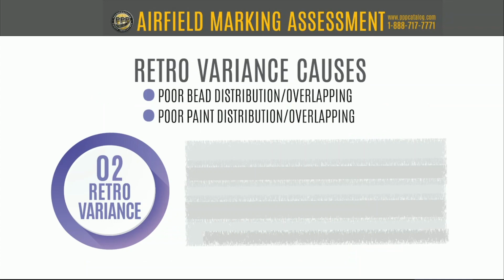If I had a choice, my primary fix would be the architectural tips in the middle and the line striping tips on the edge. But if I didn't do that, I would eliminate the architectural tips altogether and just use the line marking tips across the entire system. So that's my thought on it. Mike, if you want to follow up on that.